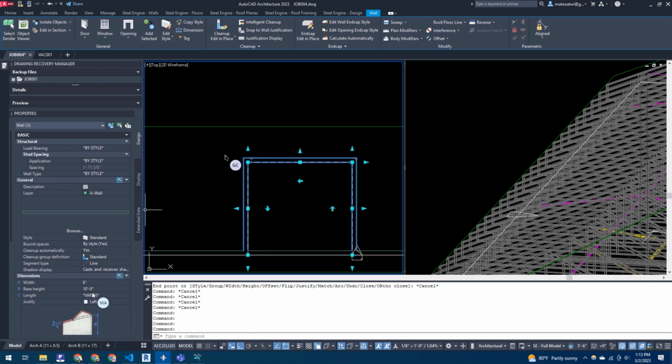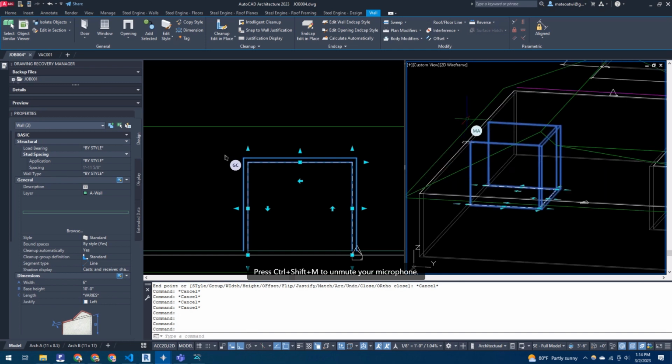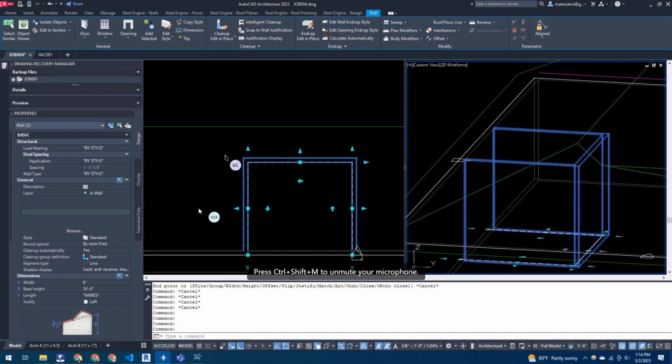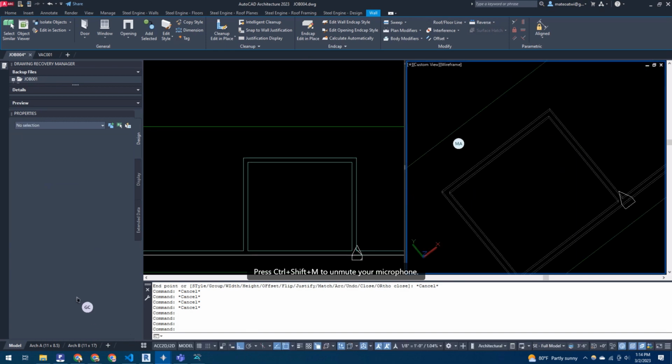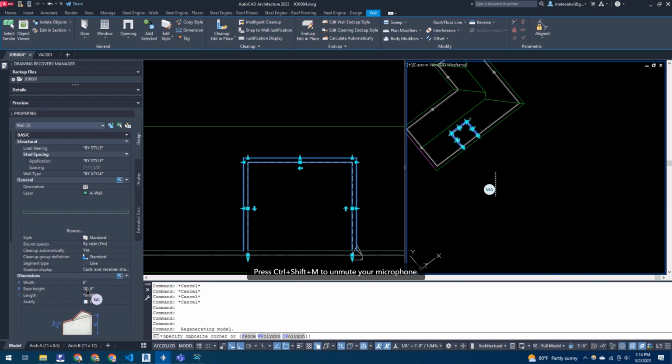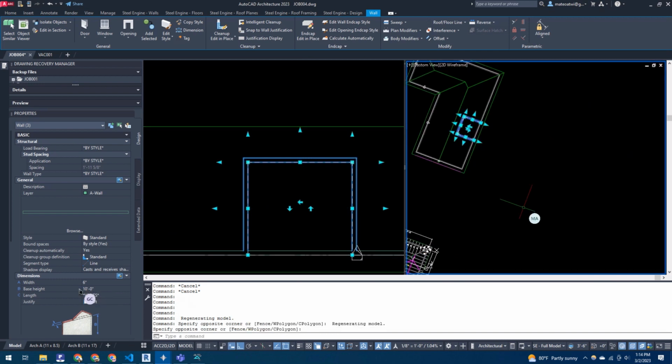So we'd put that elevation, because you have to know how tall those are going to be. Otherwise, it's not going to do anything because it's going to be under the other part. So you'd have to go in and say base height and change the base height in the properties. We'll make them 13 feet.